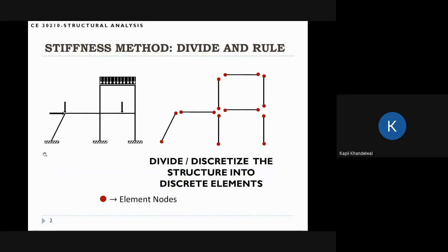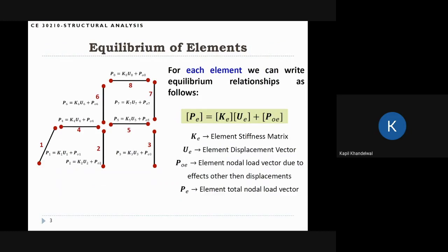element. And at the ends of the elements, here I'm showing red circles. Sometimes we call these ends nodes, and we are referring to the element nodes all the time in our class. Nodes are the endpoints of the element, and that's where the displacements are described. So now we can express the equilibrium condition for an individual element. That's easy to do. It's difficult to write the equilibrium condition for the entire structure, but for an individual element, it's easy to write down the equilibrium conditions.